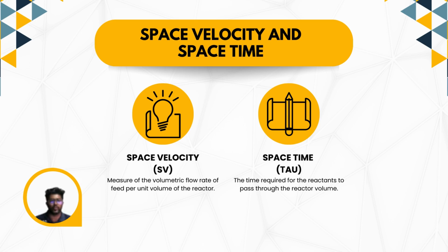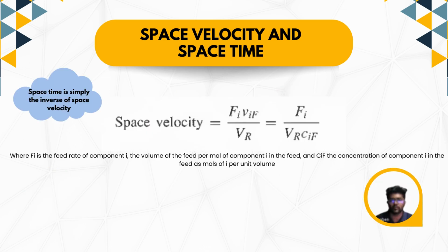Now let's discuss two important parameters in reactor design: space velocity and space time. This parameter helps determine the efficiency and capacity of a reactor. Space velocity is the volumetric flow rate of feed per unit volume of the reactor. Meanwhile, space-time tau means the time required for the reactants to pass through the reactor volume.